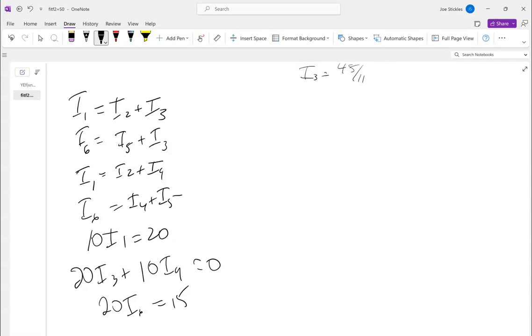When you're making the equations, do you always choose the current that's closest to the resistor to multiply that? You always go with the current that's going through the resistor. So this resistor here, the I1 is the one that hits it. This one here, the I3 hits it. So you should have a current labeled for each wire between nodes.